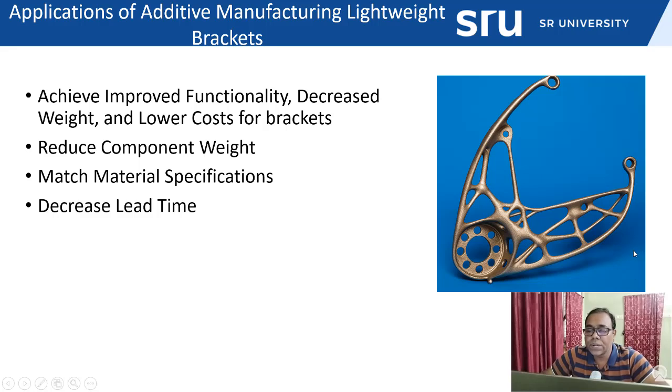But using the design optimization method, the optimization can be like lattice optimization, or can be like surface topology optimization. So here, especially in this case, surface topology optimization is performed. From that one can see that these are the areas where the loading was not applied, so no stress was